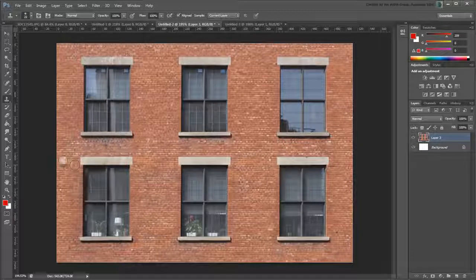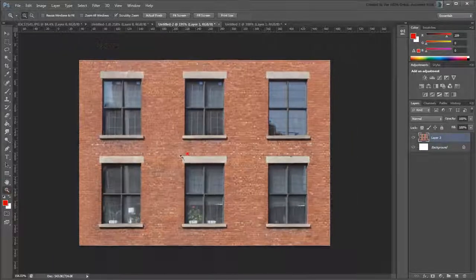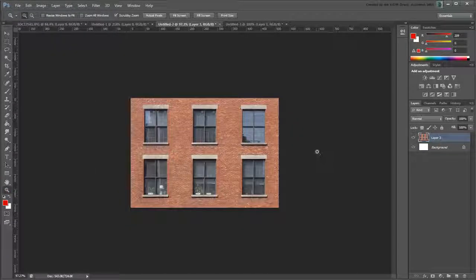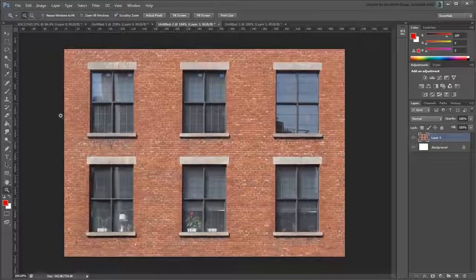Finally, you can extract other maps for more control over your renderings. Bump maps, normal maps, specular maps, and reflection maps can go a long way to refining a final render. In this tutorial, in addition to the color or diffuse maps you have, you'll also be dealing with reflection maps.